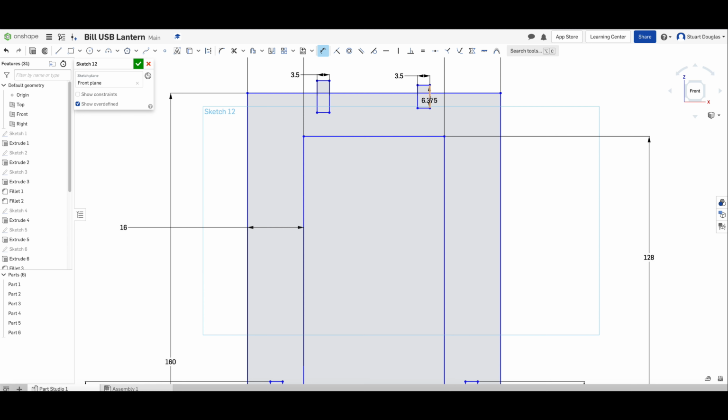So that is this rectangle, this side here, to this side should be 21.25. Let's repeat that on this side, 21.25. And lastly, we want the depth of our rectangle from the bottom here, from the top of our work, to be 6. Let's repeat the same process on this side. Okay, and so it doesn't matter on the height of these 2 rectangles, it matters on the depth of those 2 rectangles. Let's zoom out.